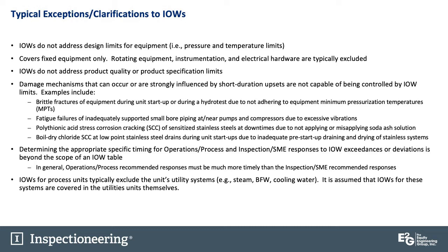What are some exceptions or clarifications to IOWs? What do they cover and not cover? IOWs do not address design limits for equipment, pressure and temperature limits. It's an interesting point, but most failures in refineries are not because we exceeded design pressure or design temperature. Our construction codes for refinery equipment are quite conservative with their safety factors, and it's pretty rare that we fail equipment by exceeding pressure and temperature design limits. It is much, much more common that we fail equipment because it's degraded in some way. It's corroded. It's developed cracking, that sort of thing.